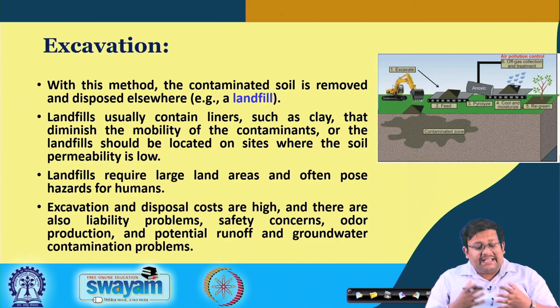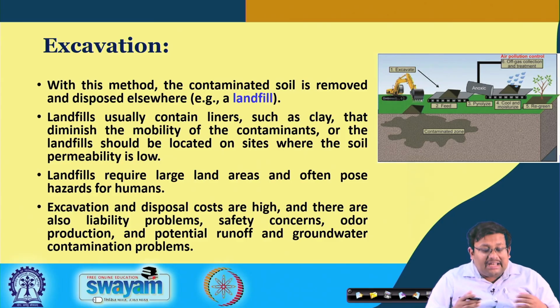A landfill usually contains liners such as clay that diminish the mobility of the contaminants. We have already talked about the organoclays. So, we put the lining with the help of clay to contain those contaminants within that area, or the landfill sometimes should be located on sites where the soil permeability is low.